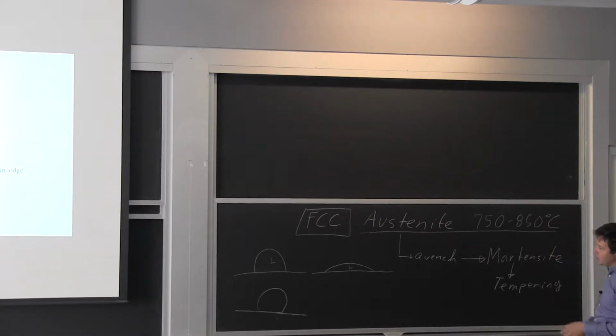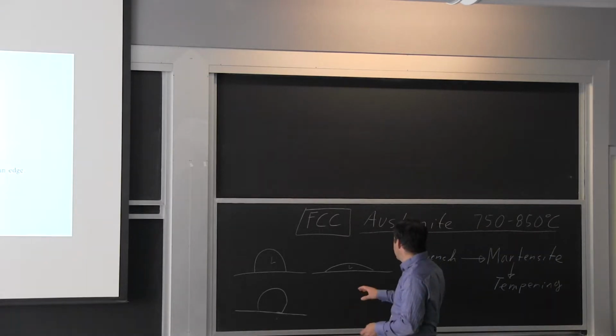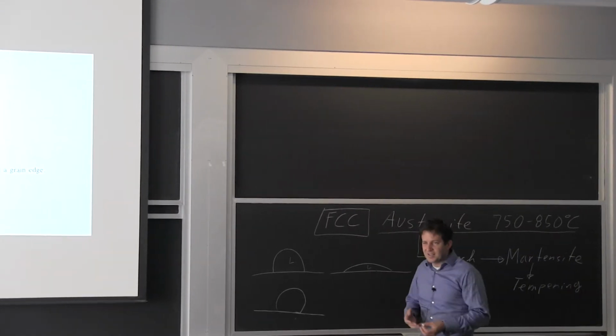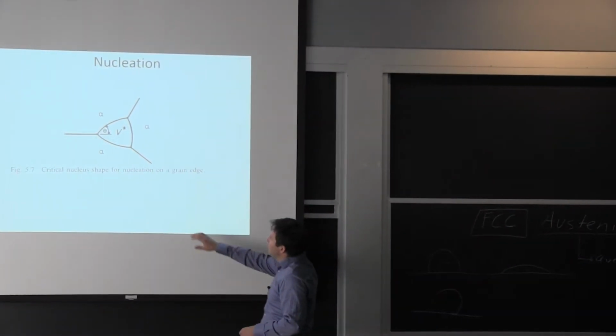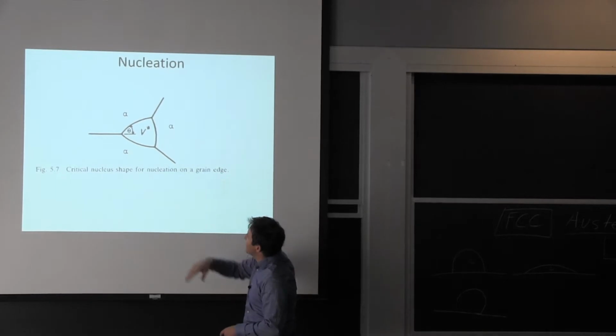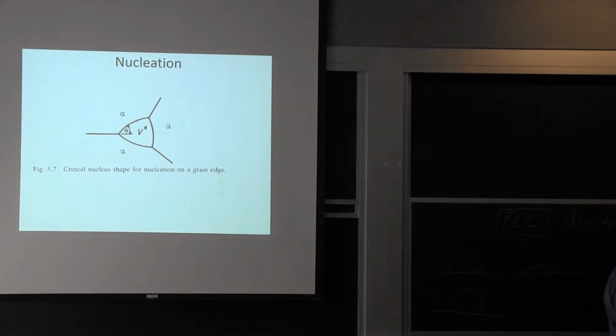The nucleation stuff is slightly different because essentially you have two conditions. You're going to try to grow from something existing in your microstructure, and you're going to have that critical size. So here it's shown as a grain boundary. You start from a grain boundary, and you try to grow this new structure. And you're only going to grow it if you can assemble, say, 1 million atoms together and organize it.